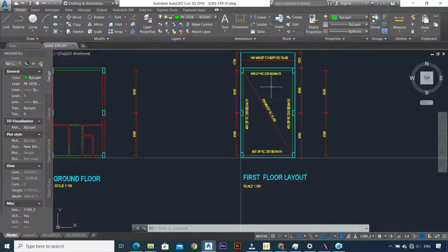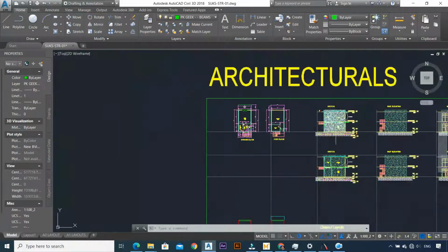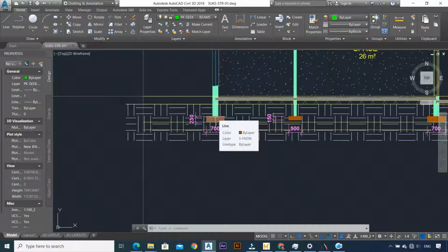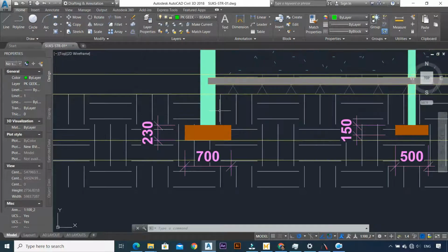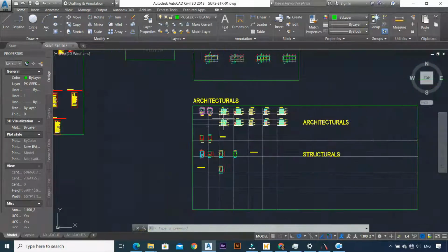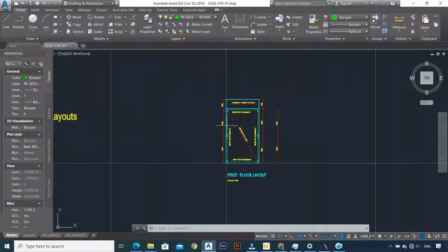That is what you normally have to do, because you want to see the load that is going all the way down to the foundation, because this will help you to establish what type of foundation you need to use, and also to check if the bearing pressure of the soil will be enough to cater for the loads that are coming down. This is the difference between your strip footing, your pad footing, your raft footing, and also using piles. So that is why we do the preliminary tributary areas that we use for the distribution of the loads to the foundation.